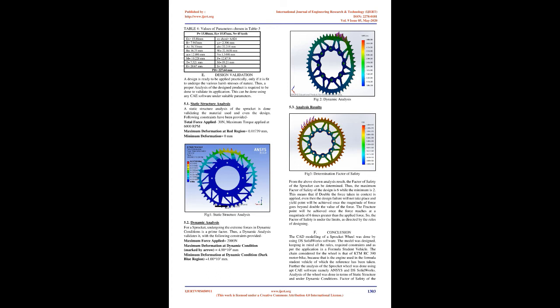8. Line psi was drawn equal to E. 9. Draw arc XY and line segment YZ. 10. Locate the offset point made above and make a new circle of radius F. 11. Joining the tips of the lines was done and the required shape was given. 12. Follow-up trimmings and others to get the proper shape. 13. Mirror of the above line and arc was done to get the desired drawing. 14. Array the tooth with the pitch line of the wheel. Here we have used 45 teeth, thus array it 45 times to get the required sprocket wheel.